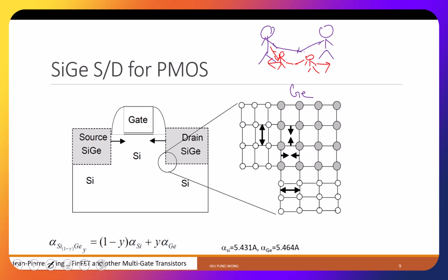So the silicon is going to get compressive stress. Tensile stress, sorry, right? Because your silicon are the kids, they are smaller, so tensile. And this is going to get compressive stress itself. So this part is compressive because I have more silicon germanium.